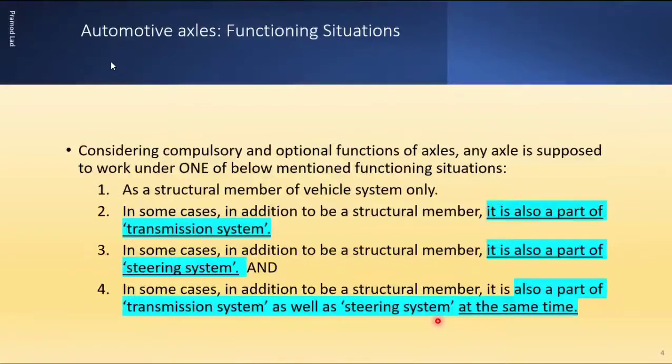And the fourth is that in some cases, in addition to being a structural member, it is also a part of the transmission system as well as the steering system at the same time. So there are certain situations where the axle is a structural member, it is part of the transmission system, that means it has a differential gearbox also, and it is a part of the steering system also at the same time. This will particularly happen when the axle is at the front and it is the live axle.